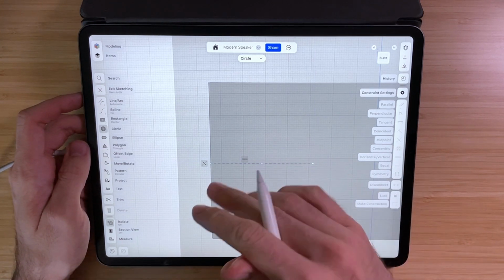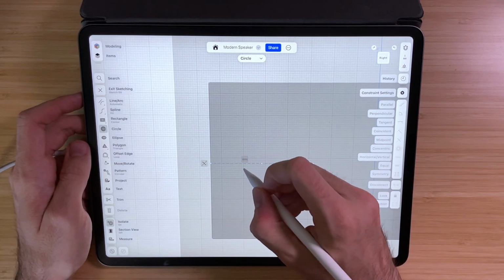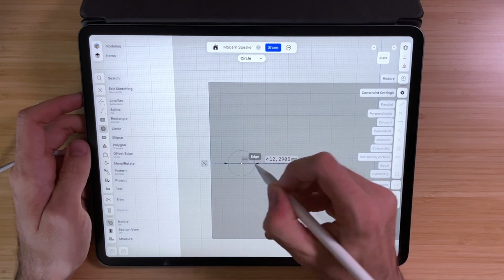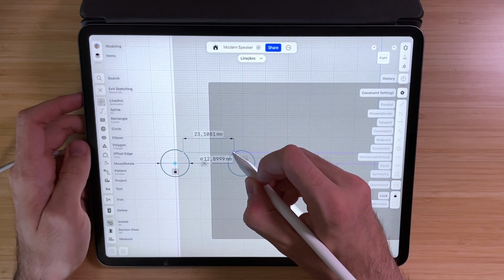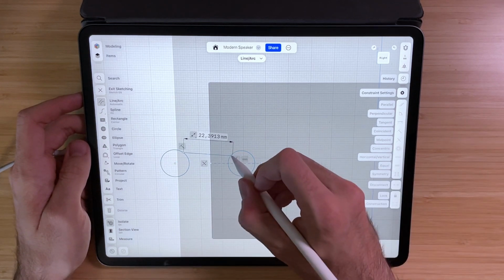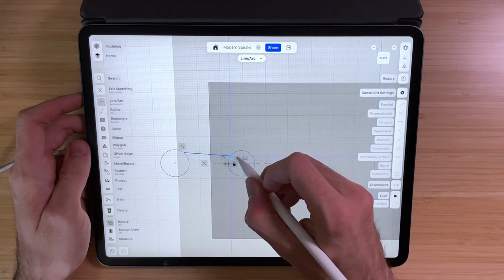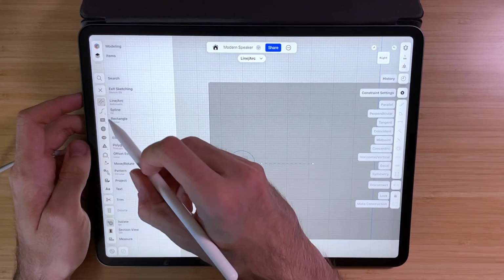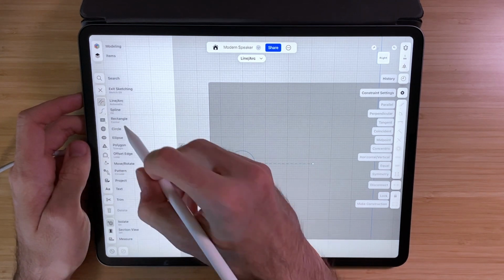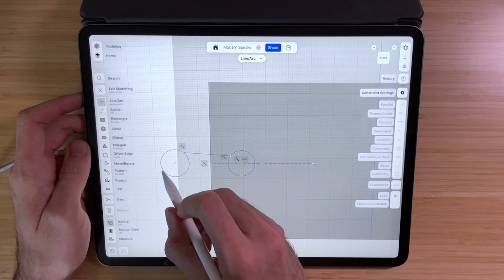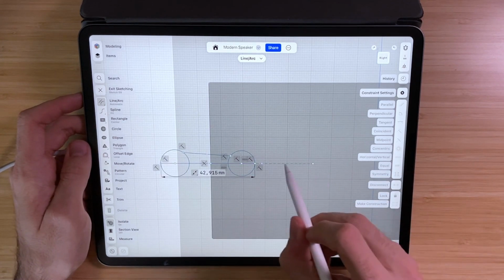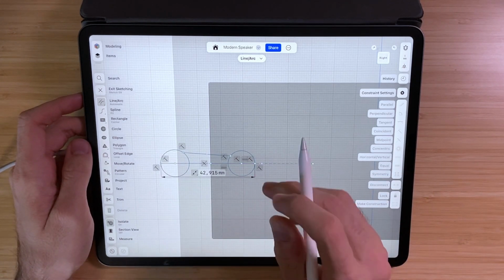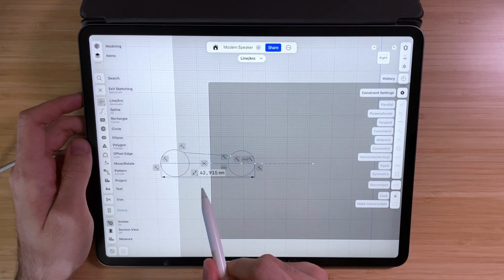Next, we want to just rough in our switch contour. So just create 2 circles and we'll connect the circles with a line. Make sure that the end of the line is also on the circle. And we'll also create a new line which goes from one side of the circle to the other. So basically just crossing the whole sketch. And we'll not make this a construction line.